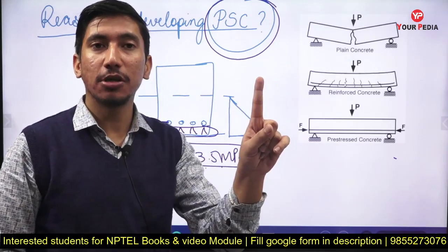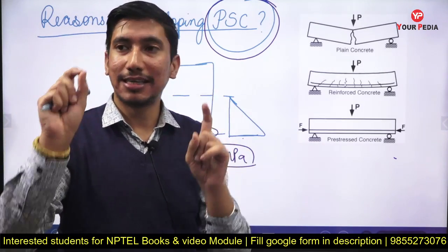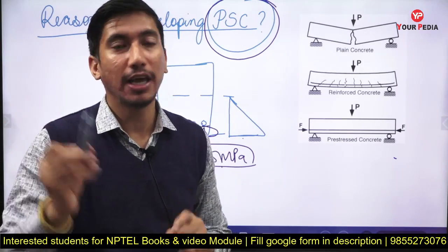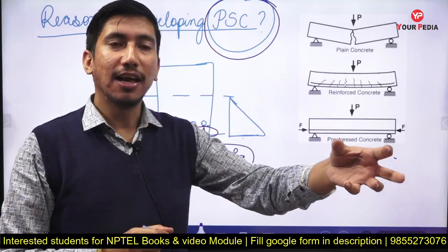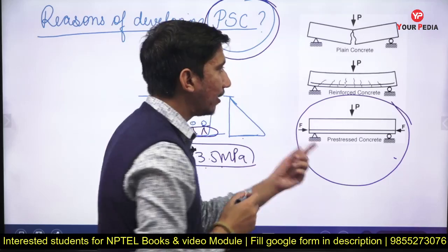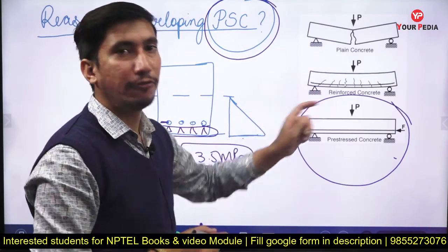So the failing is also important and the cracking is also important, because cracking is also one serviceability criterion in RCC, if you can remember. So it will also not fail and it will also not crack. That's why pre-stressed concrete is better than both plain concrete and reinforced concrete.